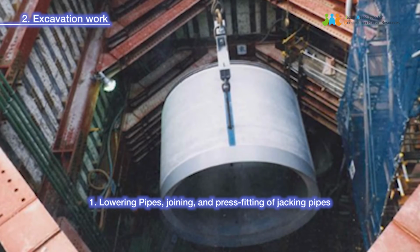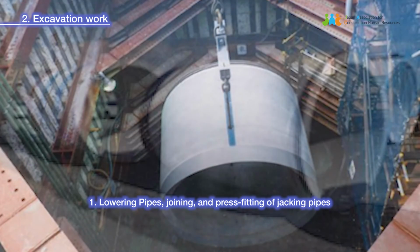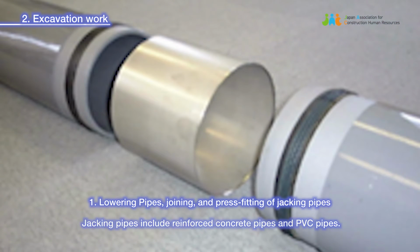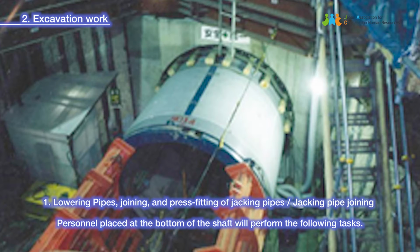1. Lowering pipes, joining, and press fitting of jacking pipes. To lower the jacking pipes, use special hoisting hardware or wire rope. A qualification is required to operate the crane. Jacking pipes include reinforced concrete pipes and PVC pipes. Jacking pipe joining. Personnel placed at the bottom of the shaft will perform the following tasks.